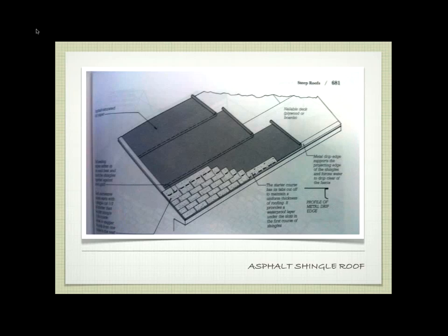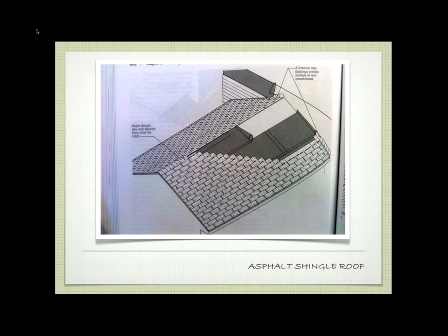The problem is if you have a leak and you've got to tear it off, you've got to start from the top and tear it down, or find a way to slip underneath a particular layer. It can be very challenging. So here it is getting all the way to the top. And usually there's some kind of a ridge unit that's designed to span the ridge and fold together and seal off the ridge. Sometimes it has a vent built into it. Make sense? Eave to ridge, always.